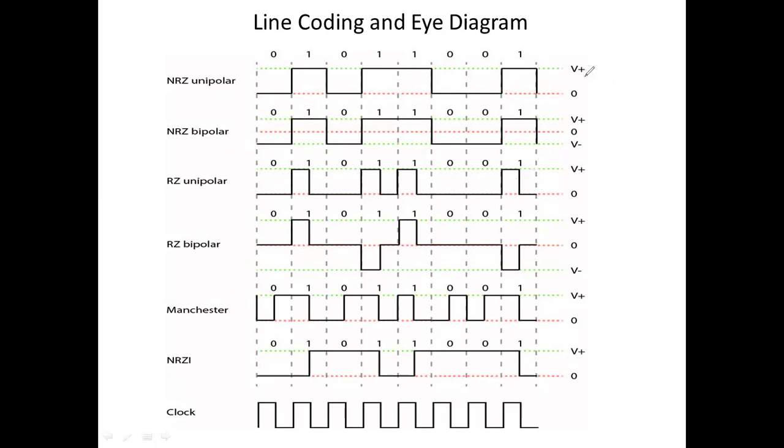And then there is one thing, you cannot go for these kind of boxes, because when you go for the codes and you want to occupy the entire time interval in boxes like this, we know in the frequency domain what's going to happen. We know that the DFT of a rectangular pulse is a sinc pulse, and the DFT of a sinc is a rectangular.